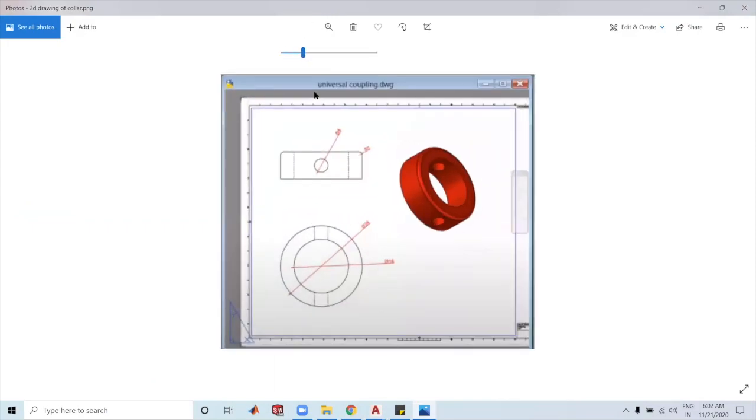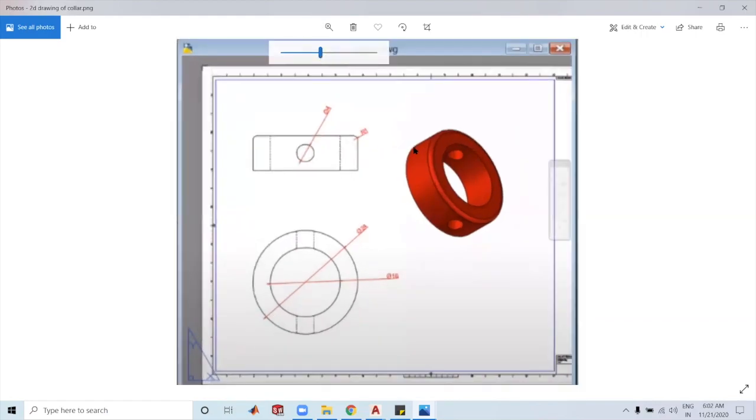There's a particular dimension which is missing over here. So we need to draw an outer circle of 24 units in diameter, while the inner circle is of 16 units in diameter. There's this particular thickness which is missing, and we are assuming it to be 8 units in thickness. So just keep that in mind. We are using 8 units as the thickness of this.